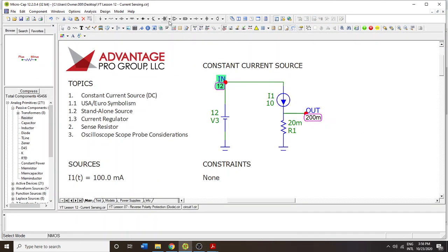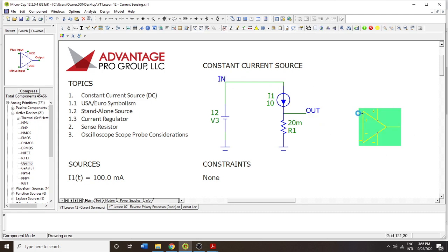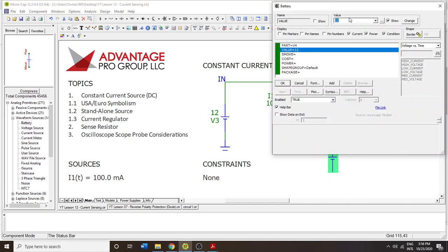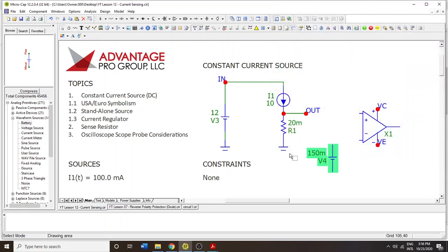So if I wanted to imagine that this is a comparator of some kind, then, okay, well, on one terminal, I might set this to, say, 150 millivolts with respect to ground, and then this terminal here is going to connect to one side of the comparator, and then I'm going to get some sort of output that's going to switch between VC and VE depending on which one is greater.